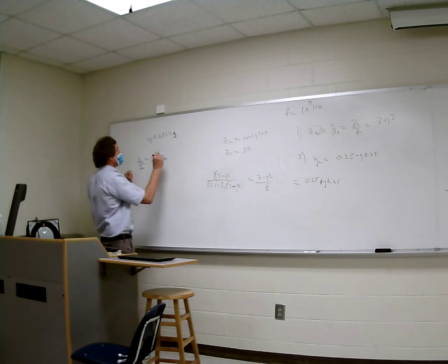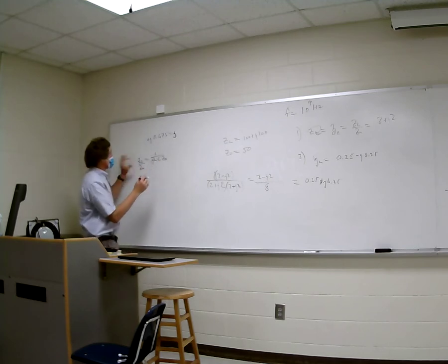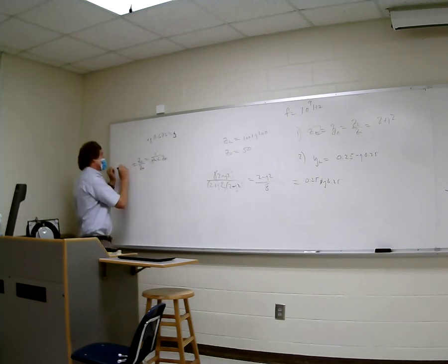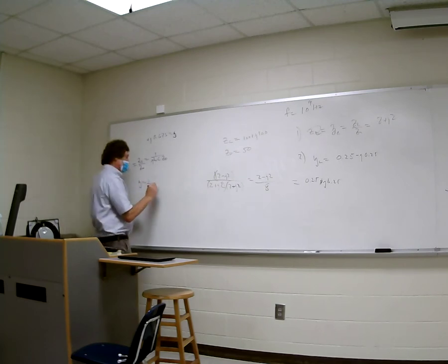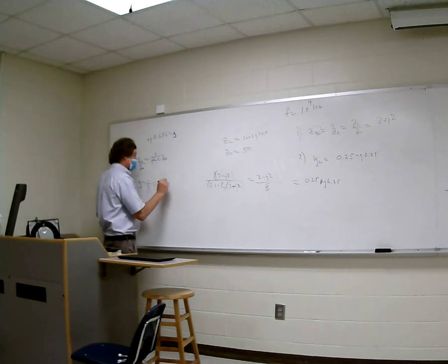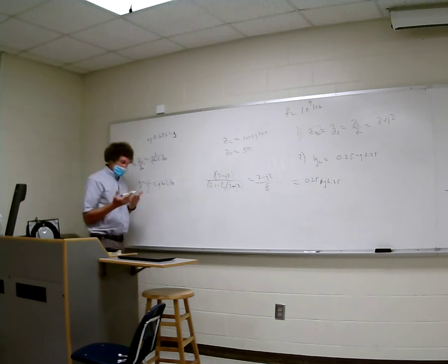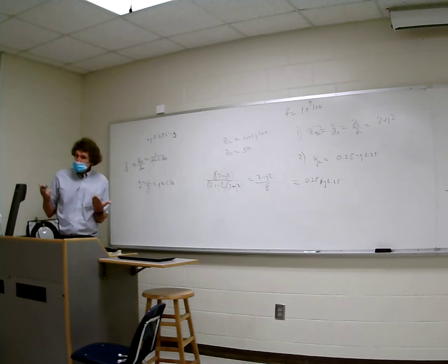Just set it equal. Well, I'm sorry. This is the normalized impedance, right? But we want admittances, 1 over Z normalized. This is unnormalized, so we have j omega C Z naught. That's 1 over the impedance, the admittance that's normalized now, correct, class?